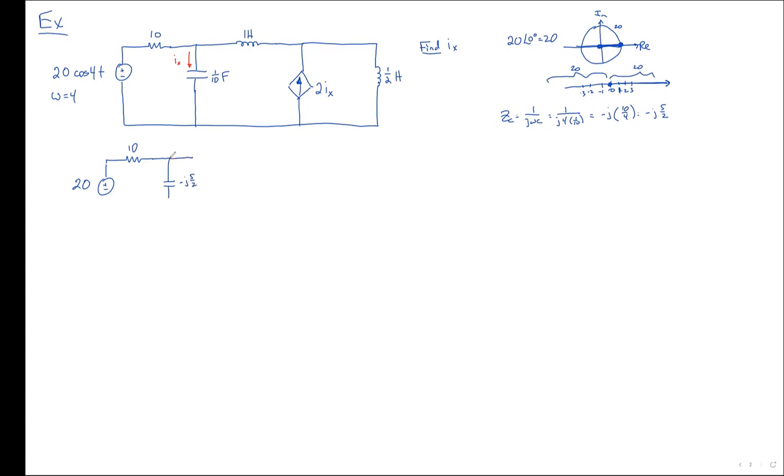I actually need to ask, when I was looking at this, why is j negative in this instance? Because 1 over j is equal to minus j. Okay, that makes sense. How about this? The impedance of the inductor? Jonathan? That'd be j omega L. So what is that? 4j. That's it. Only because we're electrical engineering, we say j4.